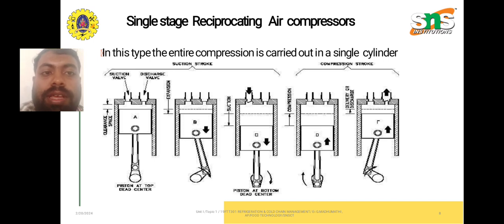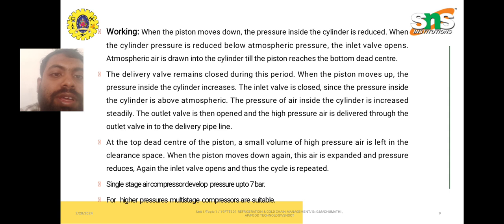In this type, the entire compression is carried out in a single cylinder. The air passes through the suction valve as the piston moves down, and then the piston moves up, the air is compressed, and it is discharged as high pressure gas. In the starting process, suction takes place, and in the final process, compression takes place. This is the working principle.